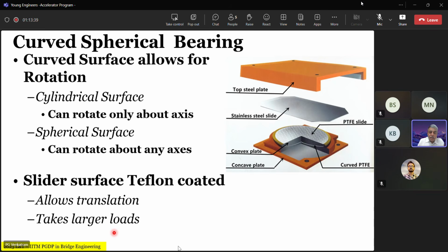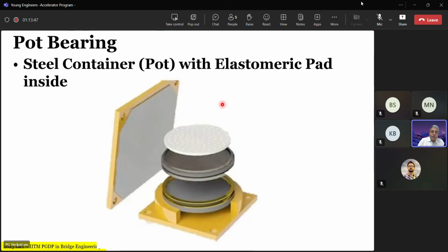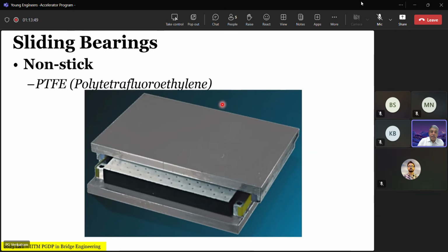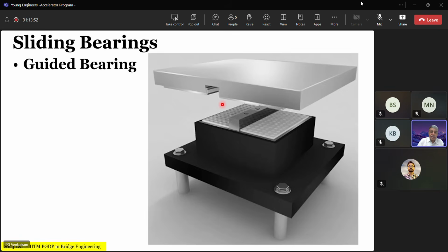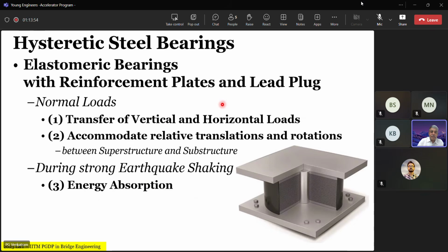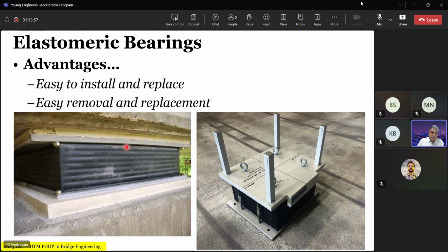Okay, basically to understand that you have to understand the load transfer mechanism, right? So let's take a look at this bearing. This bearing is easy to understand, right? There's a load here and there is a flexible material here. If this base is even not properly grouted, there is enough flexibility in it to accommodate the vertical load. Okay, this base is not grouted.